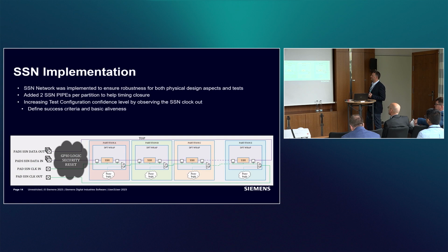Then I thought, there is one signal that goes throughout the design, in and out. Maybe I can use it as a shuttle. So I decided to add a mux here, and I connected in each partition the PLL clocks and shift clock. So I will be able to see the actual shift inside that I configured, because the internal shift is different from the SSN clock.